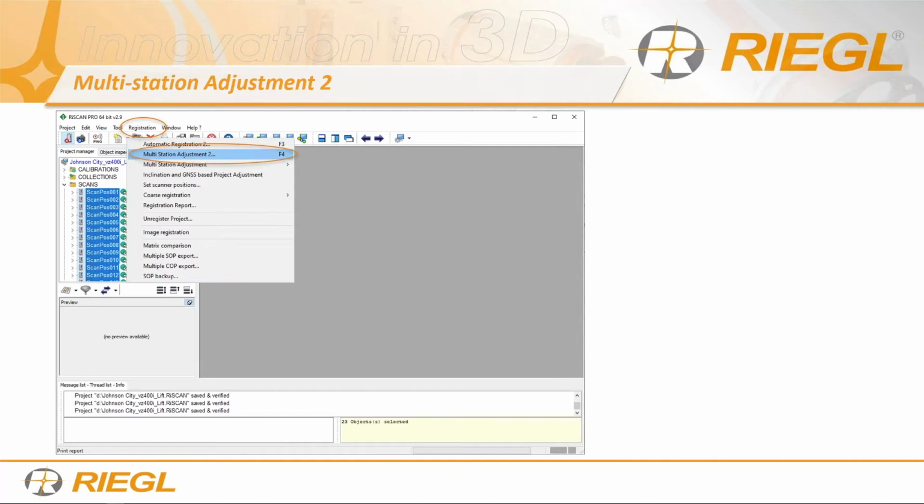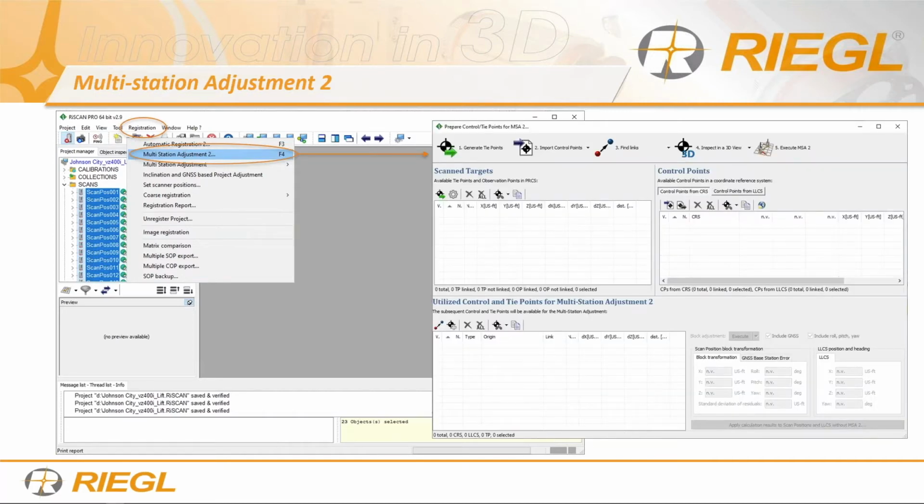Once you select that, you're going to get a dialog box, and it looks completely empty. Now, those of you that are not aware: when you import, download, and convert the raw data from the scanner, it'll ask you for two options. One is to define your geosys manager, and the other one is to define your type of targets, right? If you've already defined your type of targets, you can almost skip step number 1, but I'm assuming you don't, so we're going to look at step number 1, which is defining your targets.